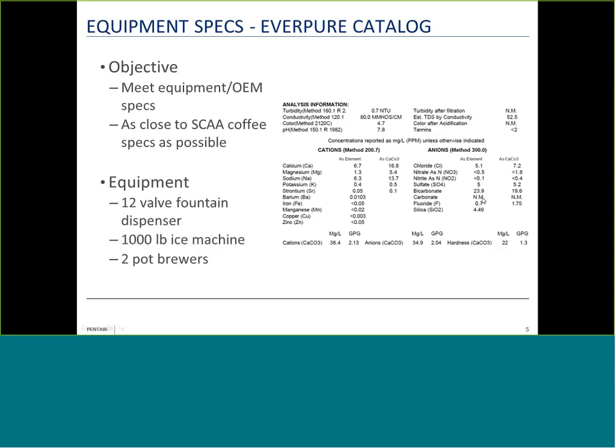And then coffee, it's in range, a little low. This is one place, if you have a very discerning customer, they may even want to add mineral content back here with something like a 7cc cartridge after chlorine and chloramine filtration to remove that taste and odor impact. But other than that, this is standard base carbon filtration.